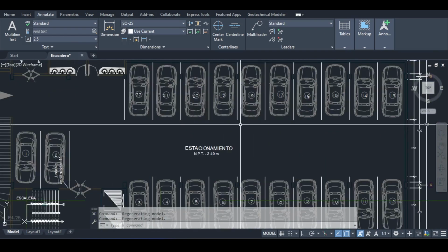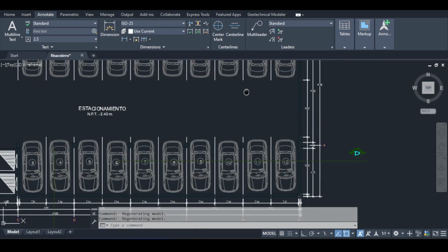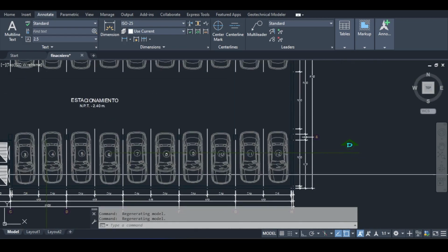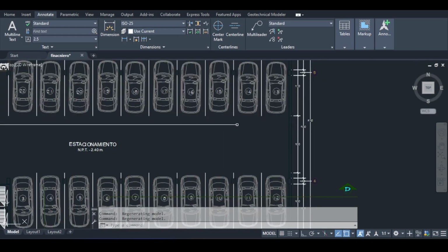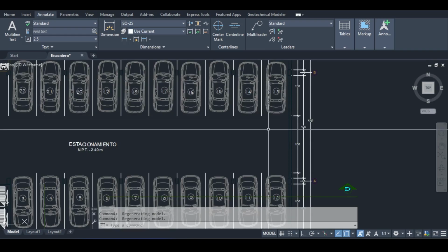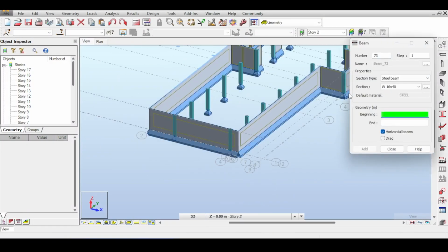Okay, how would I try to alleviate the stress on the slab? If I do a one-way slab, which seems to be the simplest, I would just span my beams going all the way from here to here and span the slab in this direction, which could be a good way. I will start modeling first. I will model here the option of having a one-way slab first.